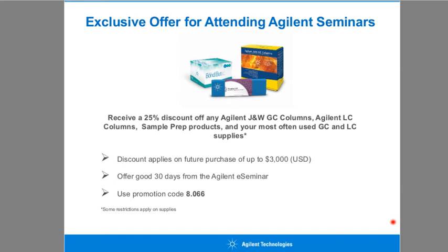What should be the liner and liner volume if we use sample injection valve for gas sampling? And apparently they use freons. We use low and high sample volume, like 20 microliters and 1,000 microliters. With that, if you're using a gas sampling valve, again, you're already injecting a gas. You don't have to worry about the sample itself vaporizing and the volume itself expanding. So really at that point, again, your inlet is more of a throughput.